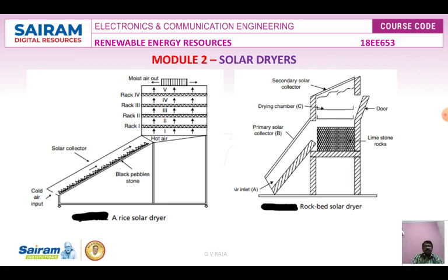The system removes the heated air from the panel and passes the air into the drying chamber. A sensor is installed in the airflow and uses thermostatic control to turn off the incoming airflow when the temperature is not high enough for solar heating. The existing system operates, and during standby the conventional fuel system can also be used on non-shining days, cloudy days, windy days or winter times. Otherwise, solar heated air can be used to dry the crops.